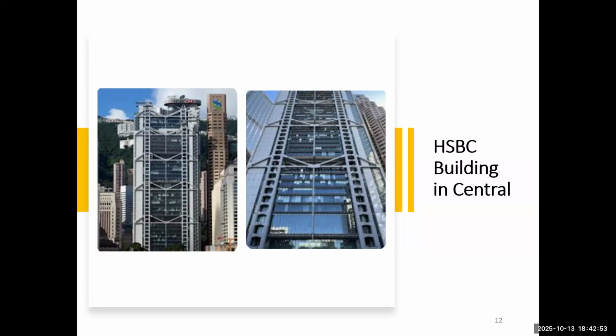Instead, a performance-based fire engineering approach was used for this building. Engineers can design a powerful smoke extraction system to keep the atrium tenable, analytically proving that this solution provides a level of safety equivalent to the prescriptive requirements, and allowing the innovative design to be realized safely.